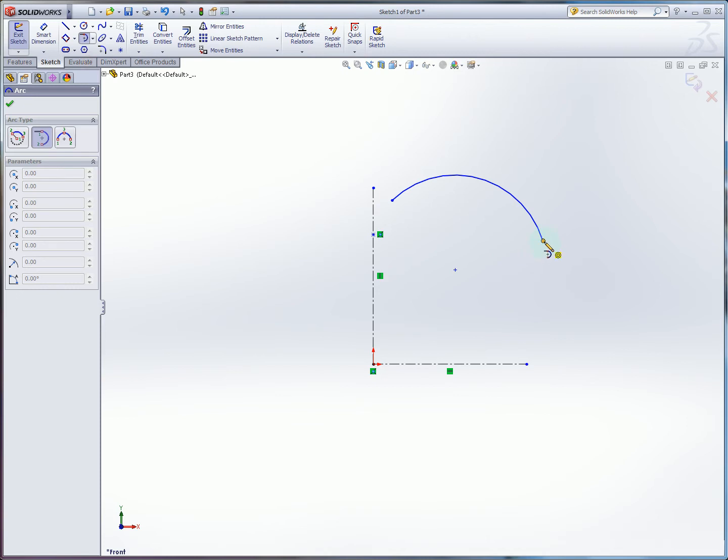With this, you basically specify the starting point, and implicit in that is the assumption that the arc is tangent to the line that you start from. So as long as you have a line to start that from, then it's easy to create a tangent arc with an arbitrary radius and endpoint that you just specify with your mouse.